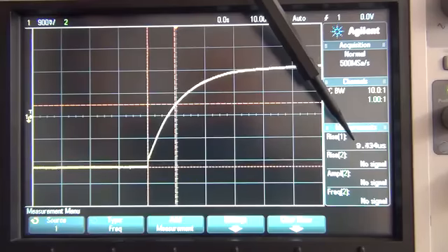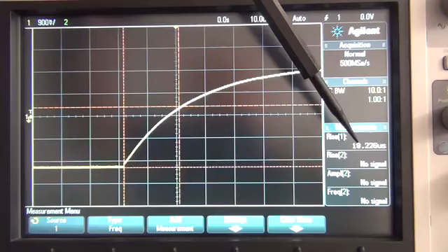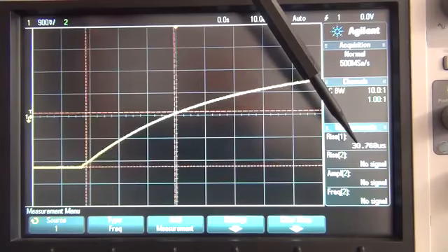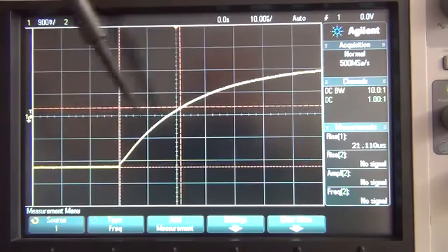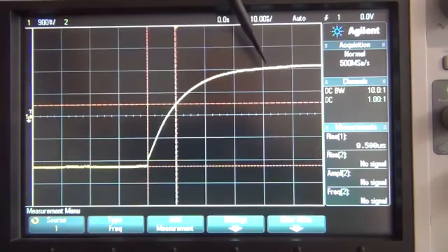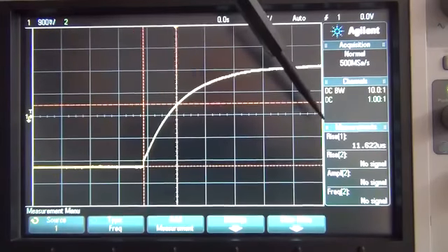And there we go, it's gone back to the kind of 8-9 microseconds. So just by turning those plates, we increase the capacitance, and then we come back and you can see how that's affecting the charge going into it, and then the actual capacitance value according to that formula.